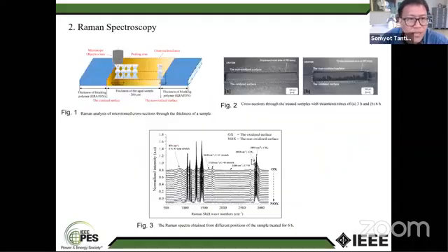So I used Raman spectroscopy to support this, through the cross-section of the polymer sheet that has a thickness of about 200 microns. I measured the chemical changes from the surface into the bulk, taking a step every 10 microns. You can see in figure 2, I cut the thin film at the micro scale and then analyze the chemical changes. Figure 3 shows the spectrum obtained from the Raman spectroscopy.